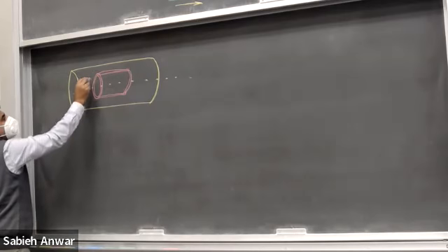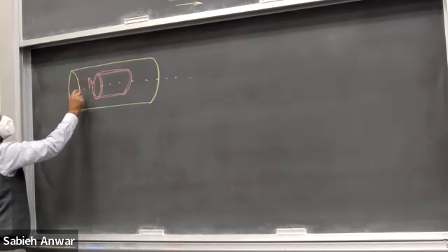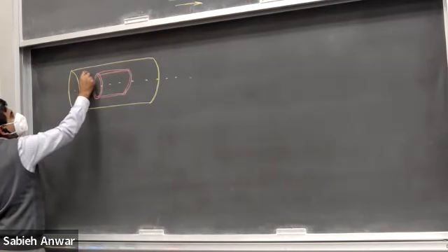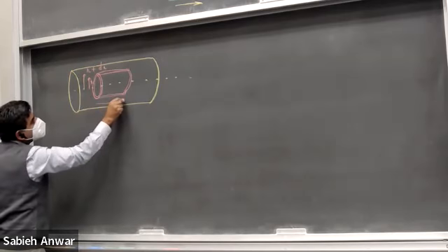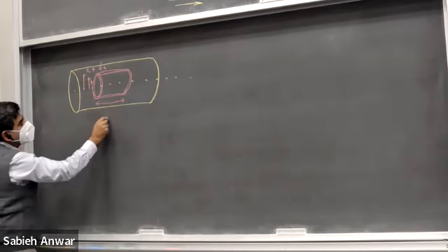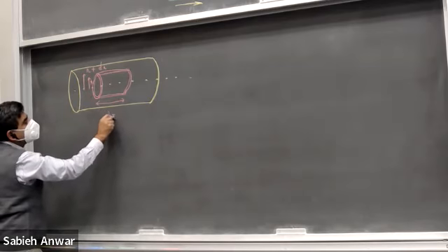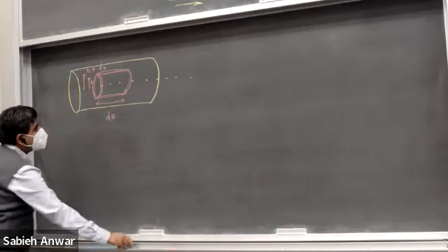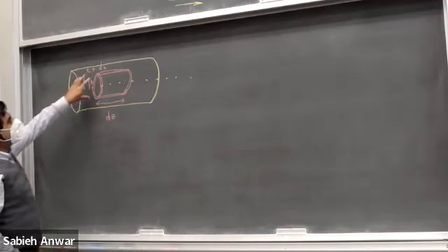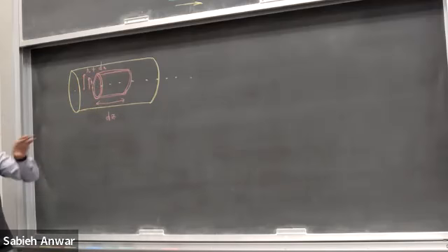This distance is r. The inner wall is at a distance r. The thickness of the pipe is dr. So the outer wall is at a distance r plus dr. The length of this small section, which I'm considering within the larger flow, is, suppose, dz. So now I have an annular pipe, a hollow pipe inside the big fluid flow, and I'm considering only the element of the fluid inside this annular pipe. And now I have shear stresses, a shear stress tau being applied to the water inside this annular ring, tau.